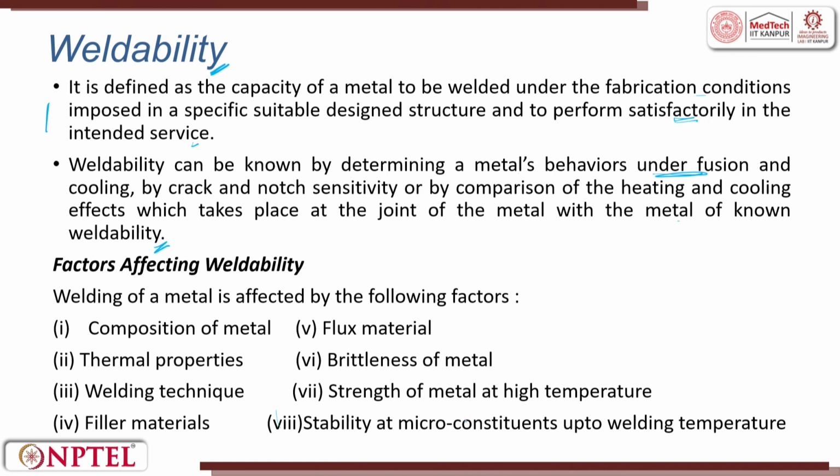So, the factors affecting weldability are the composition of the base metal, the thermal property of the metal, the welding technique which we use, the filler material we use, the flux, and the mechanical property of the material. Or the heat leading to brittleness, the strength at very high temperature, and the stability of micro constituents. All these things are factors which affect weldability. Weldability is basically that the weld can be in the service condition in a comfortable position.